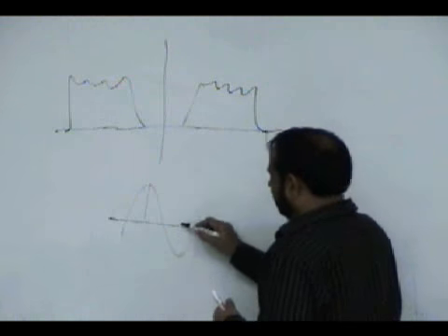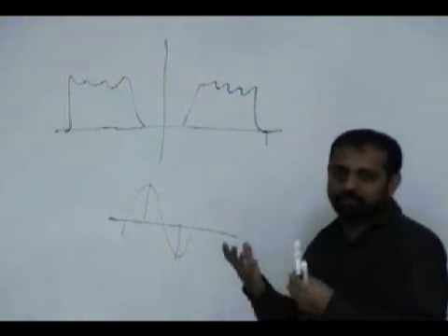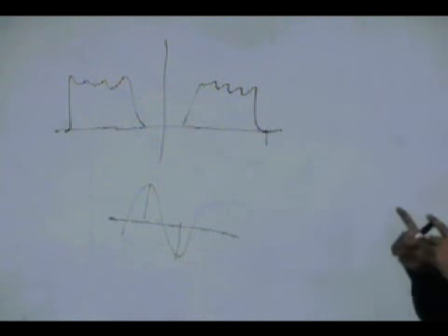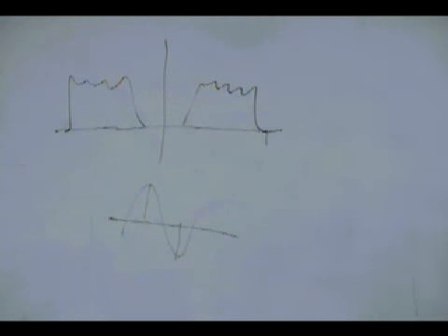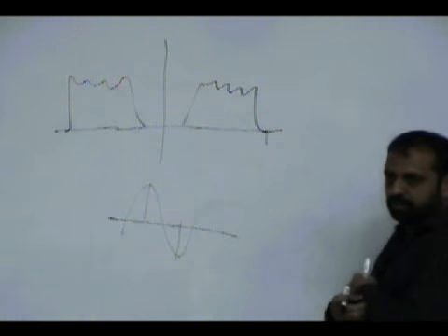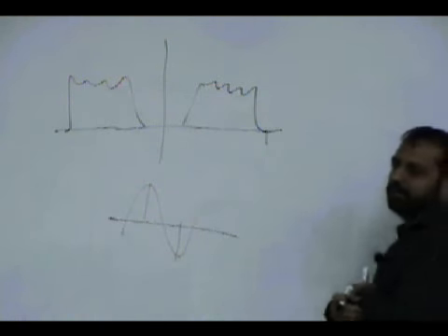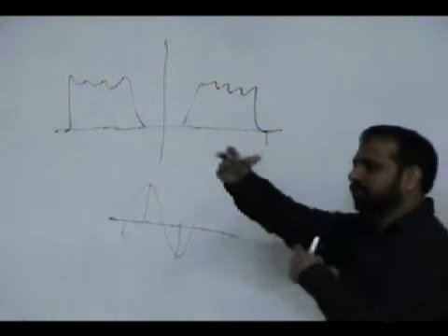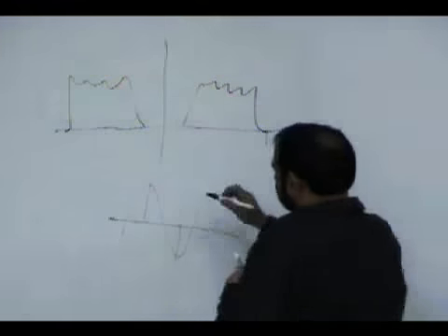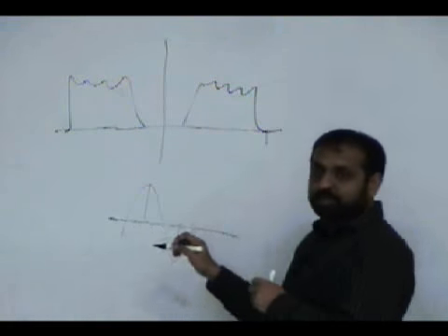2 will be fine if you sample it here. So 2 is fine, if they are not really happening exactly on 0. So 2 samples are okay, or maybe a little bit more than 2. More than 2 means 2.1 or 2.00001. After a while you get 3, but 2 are fine. Why? Because a D to A converter is a smoother.